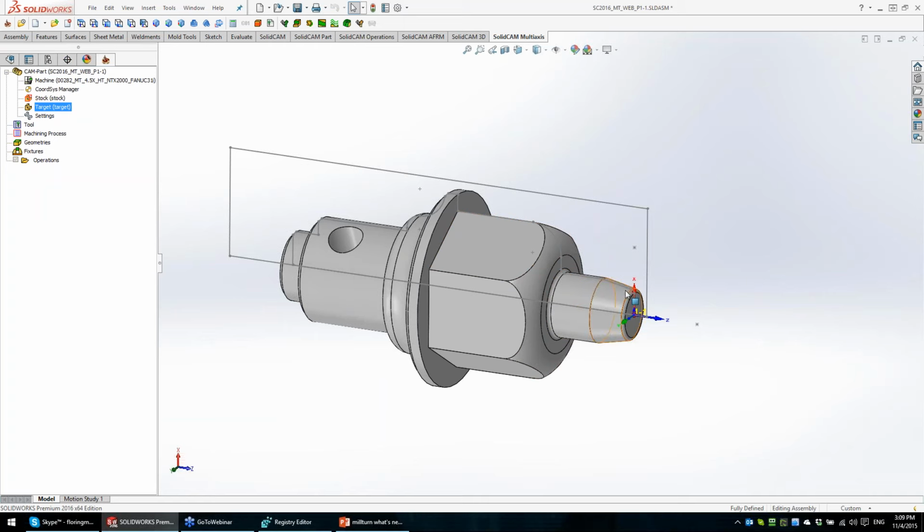I need to redefine the geometry, because the defined geometry was assigned to Mach 1, position 1, to the coordinate system of upper turret. I cannot use it in the lower turret submachine, so I needed to define a new geometry. Today, now I can work with the same coordinate system, with the same geometry, and I will demonstrate you now.